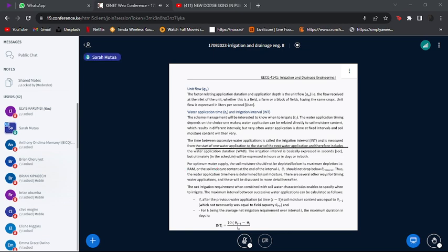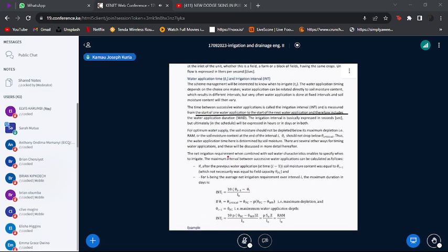I'm asking a question and I'm requesting a response. The question is, what is readily available moisture? Well, I think the readily available moisture is the moisture between the field capacity and the critical moisture content. Thank you, Kamau, because that is exactly what we are talking about. And if you look at this, that is what I have explained. It is theta FC minus P depletion factor minus theta FC minus theta depletion. So that is the maximum depletion.